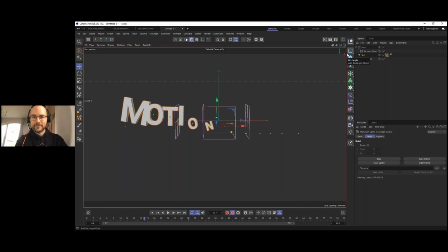I want to add something to the whole caching topic for those who might not be as experienced in Cinema 4D yet. You would also need it if you want to render via your network. If you want to spread this scene across your local network to be rendered on a render farm, you need to bake it in advance of rendering, because otherwise it will create crazy stuff that's not intended. That's everything I wanted to add.